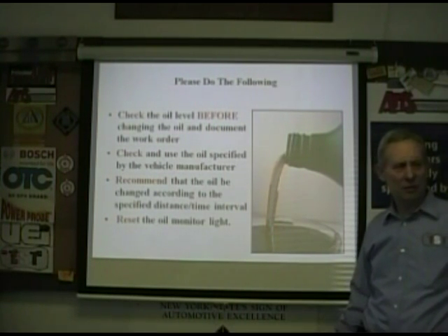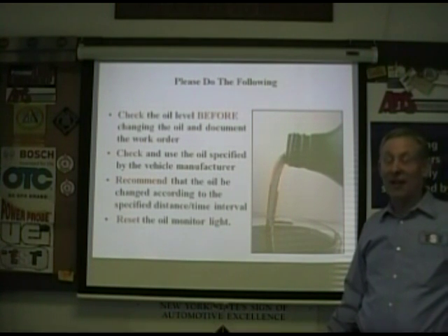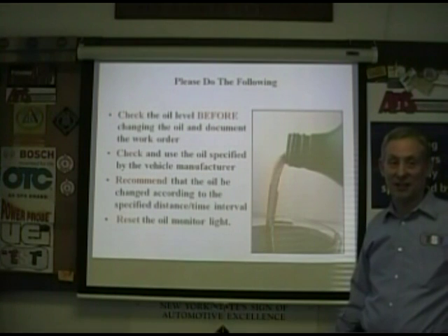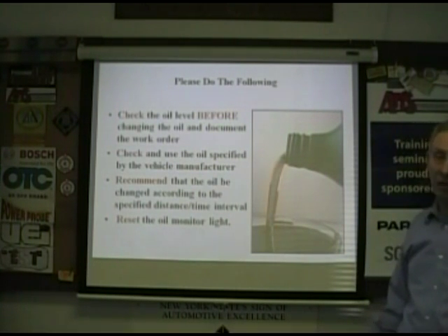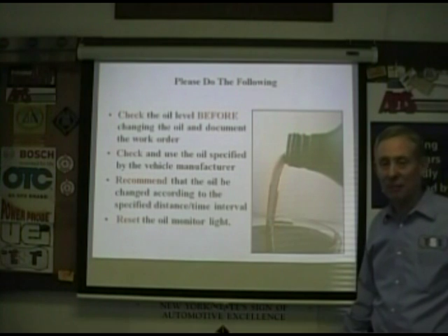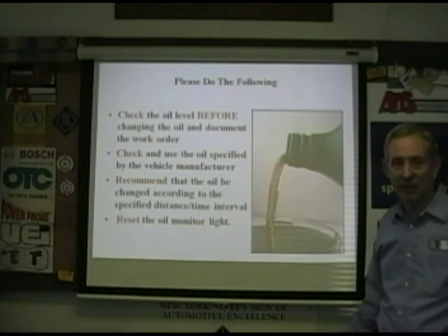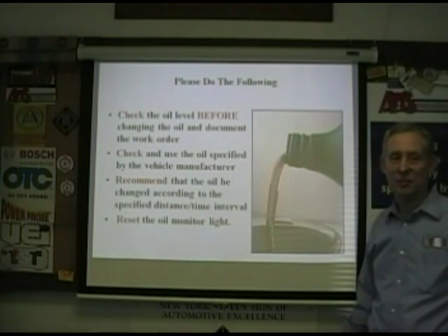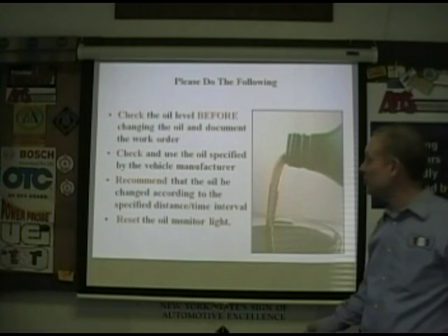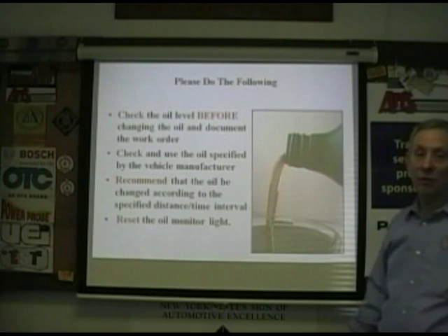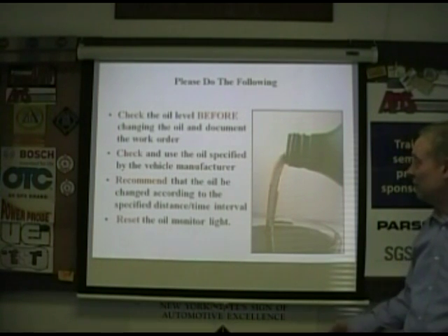Can the wrong oil damage catalytic converters? The wrong oil absolutely can damage catalytic converters. And if you start getting into PZEV cars, I think Mark Warren did a big thing on this at a previous seminar with us. You can really ruin the catalytic converter. The oil vapors have various compounds. I think sulfur and phosphorus were the biggies, but probably other things as well. They end up going through the PCV system, burning in the engine, and coating or damaging the catalytic converter.